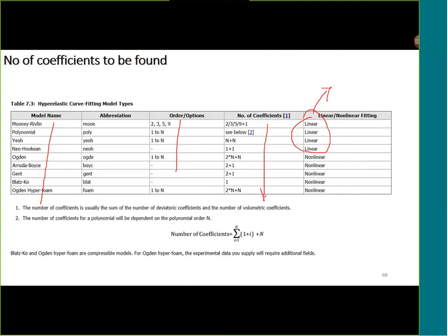In other words, the resulting accuracy of the curve fitting does not depend very highly on the initial values you provide, but for these material models which require nonlinear curve fitting, the result of the curve fitting parameters highly depends on the initial values that are provided for the iterative procedure.